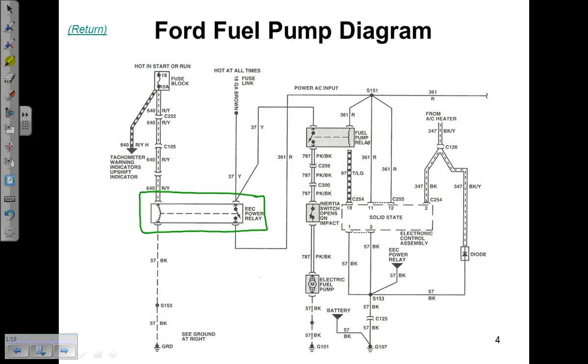So rather than having the ignition switch carry all those loads, so let's say that this is the run circuit of the ignition switch, and it's going to feed circuits all over the car. Like I said, all the relays, injectors, coils. What Ford did, instead of using the ignition switch like this, is they just added a relay in the picture. And what the ignition switch did was control the control side of that relay.